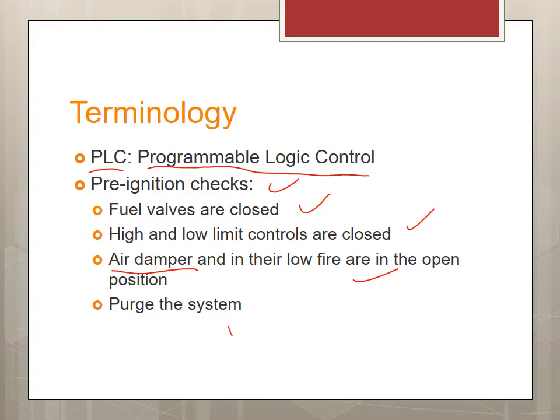That is done to purge the system. Imagine if you have a boiler, probably you did that in residential, that you turn on the system. If there's fire already in the chamber, the system will not turn on. So it does that as a safety measure. It does a pre-check before we start the firing process.